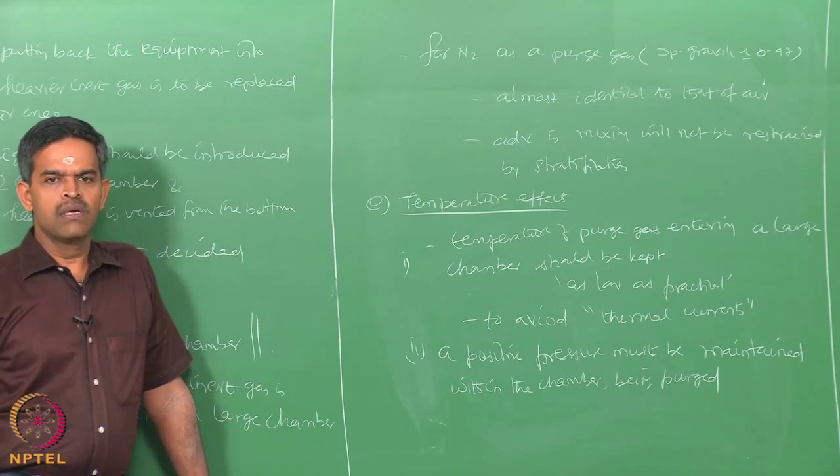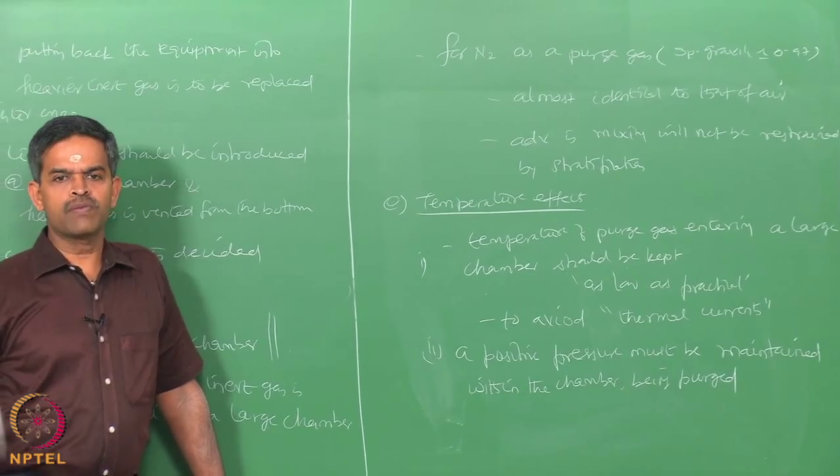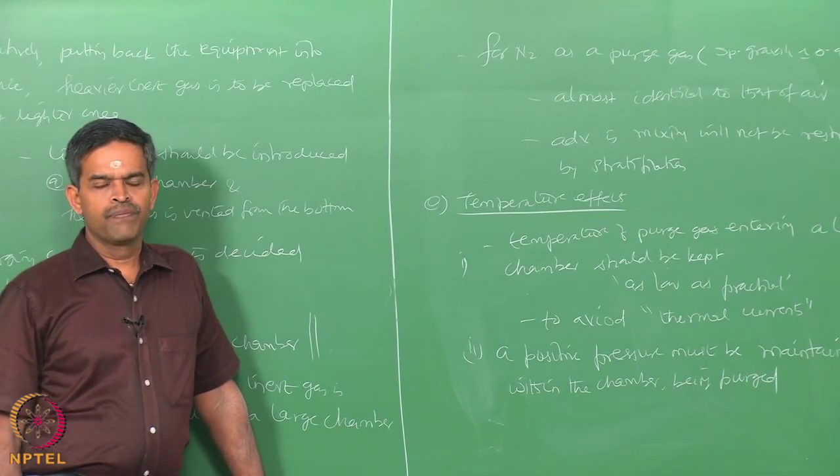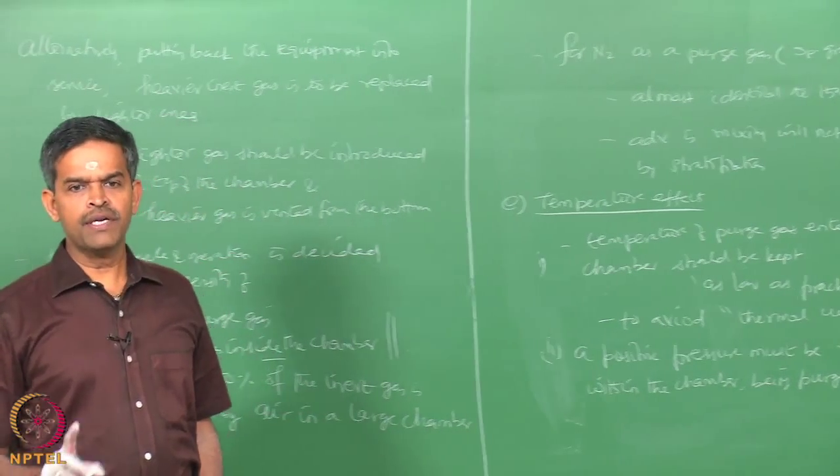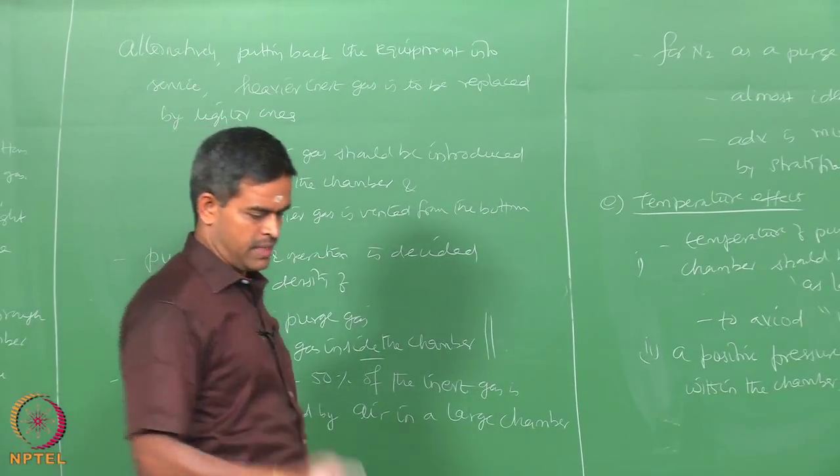Therefore, friends, whenever there is a sudden drop in atmospheric temperature, which can occur during purging of a vessel, it is necessary to reduce the rate of release of the purged gas. That is very important.